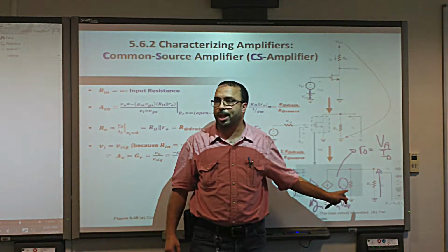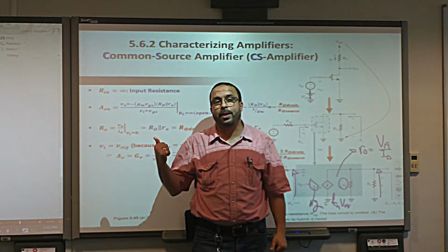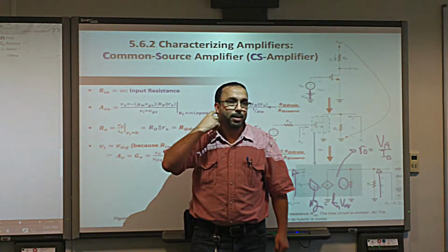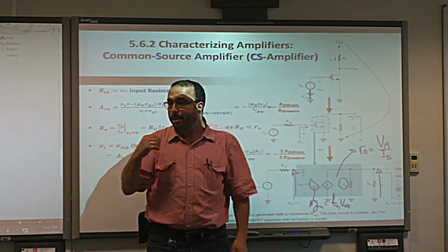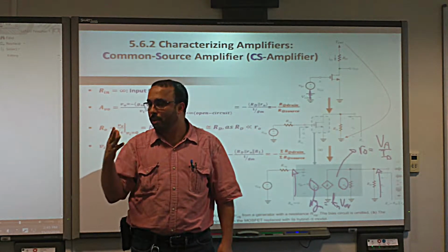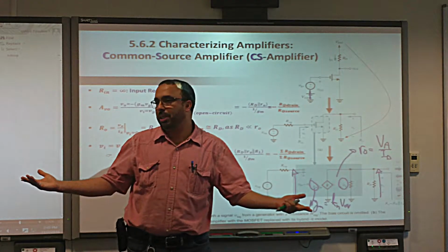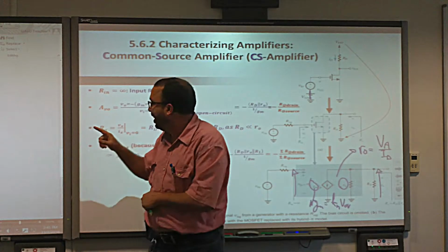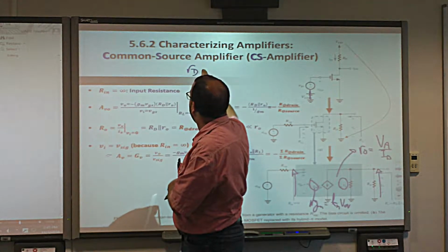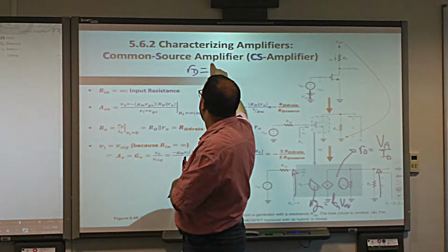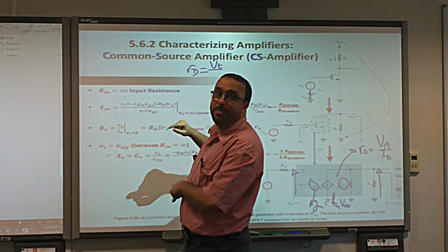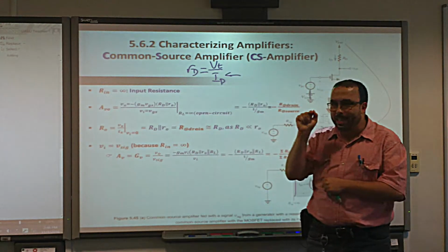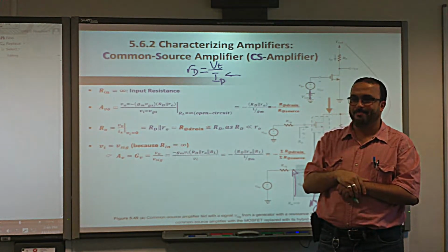And that's what we mentioned last time. Remember? The same thing that we did with a resistor, with the diode in the AC small signal analysis. So we said that in AC, we don't use DC. But where is the information about the DC? It's in the resistance, and rd, the resistance of the diode, was equal to VT, the thermal voltage, divided by ID. That's where the DC voltage comes in. It's in the value of the resistor. Do you understand?